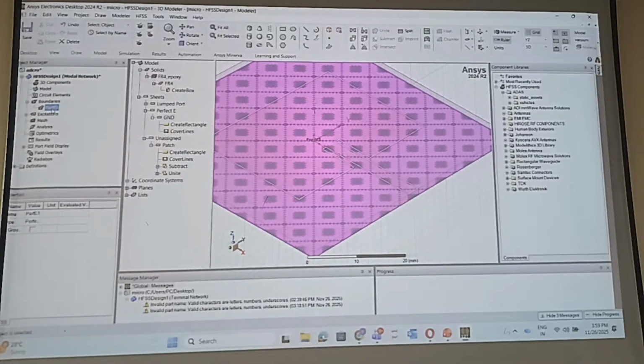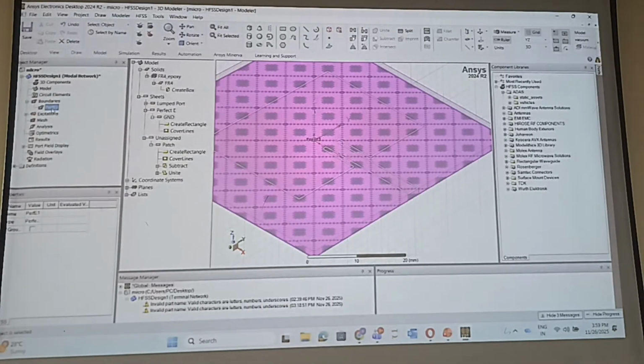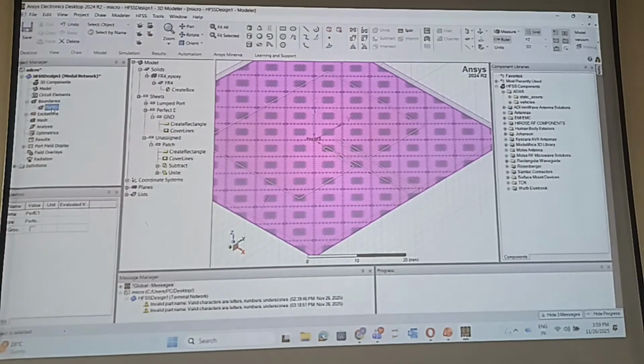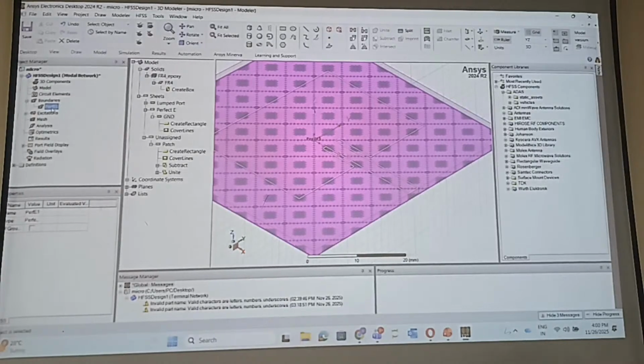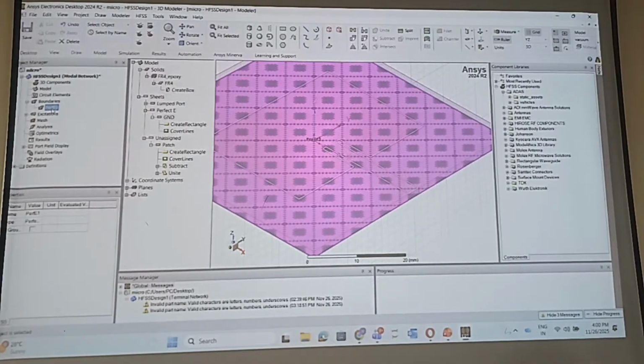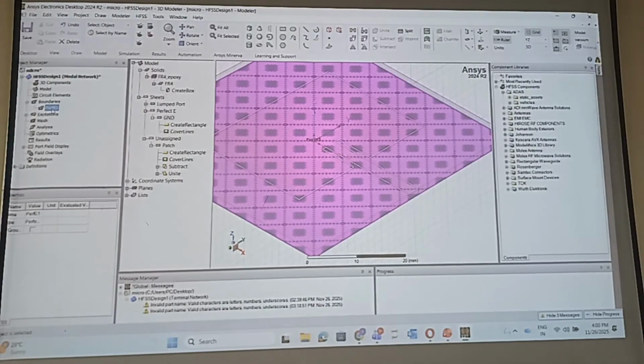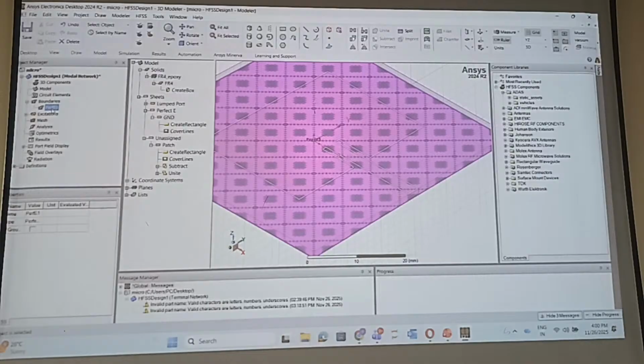Have you completed this boundary condition part? So next one, this antenna we have created for 2.4 gigahertz operating frequency. So we have to create radiation boundary box for 2.4 gigahertz operating frequency. Before, what we used to do for analysis, we used to take a box and then take a distance lambda by 4 in all 4 directions. Like calculation we used to do and create a geometry accordingly. Now it is a little bit easy.